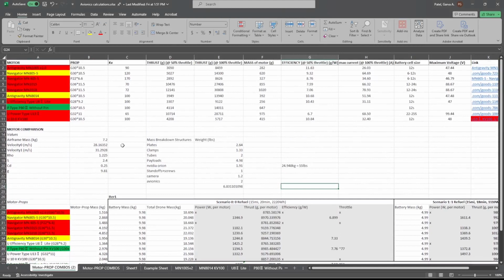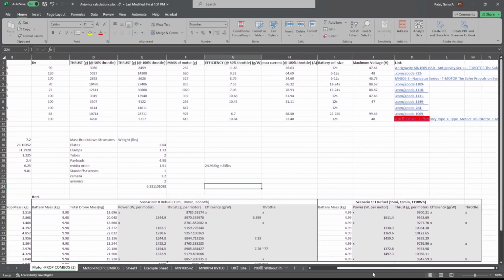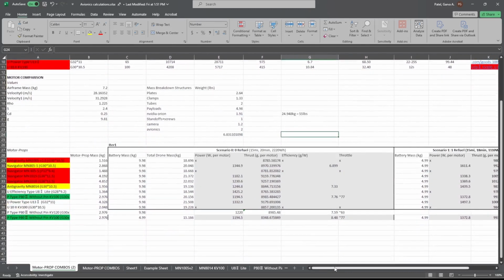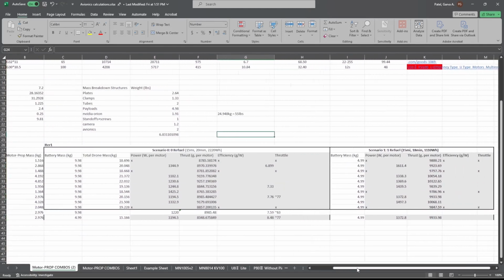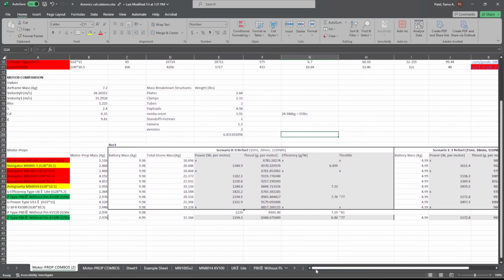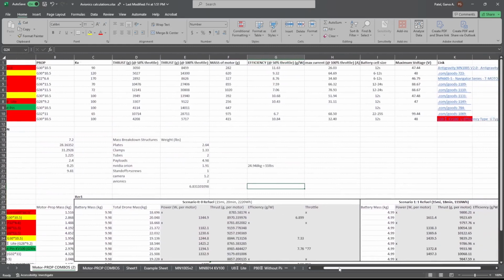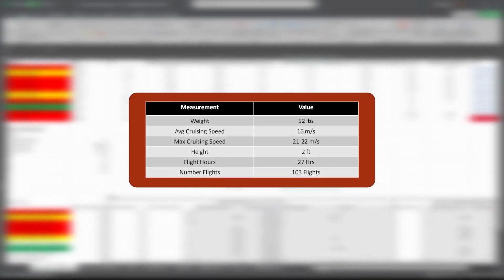Motor propeller specifications along with UAV system dynamics were implemented in a MATLAB script which calculated performance metrics across simple missions. Assumptions were made for unknown variables such as fuselage mass and battery capacity, and over multiple iterations, the script would improve the assumptions until it converged to a solution. Among all the configurations tested, the selected configuration achieved the fastest mission times.